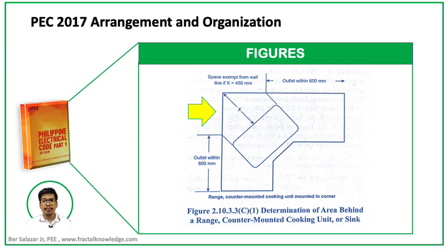It is sad that there are only few figures in Philippine Electrical Code, but that's okay. My suggestion, however, is for IIEE Electrical Committee to create another appendix of figures that explain some part of the code, especially some single line diagram where fire pump should be put in a single line diagram. There's a lot of interpretation in Article 6.95 fire pumps. This can be cleared and resolved in one single line diagram where all electrical designers should follow.